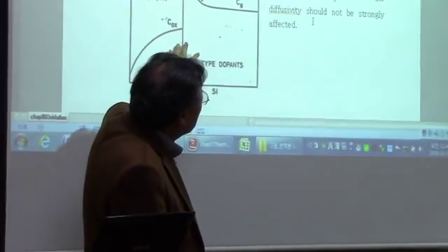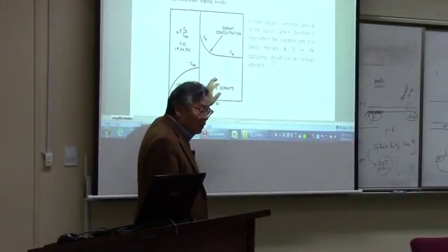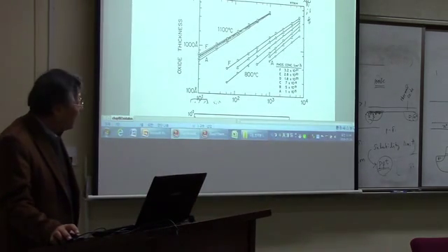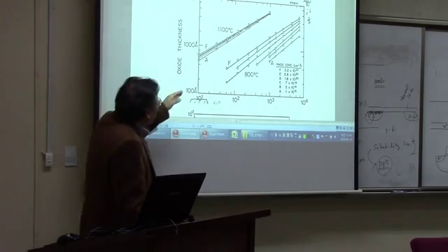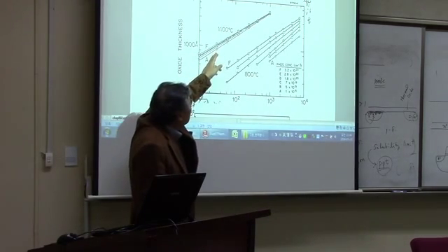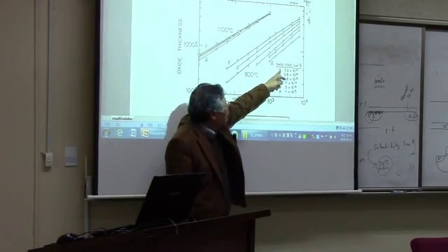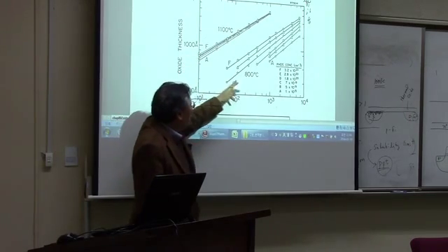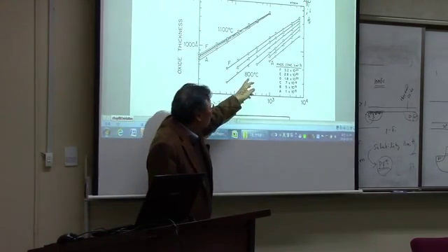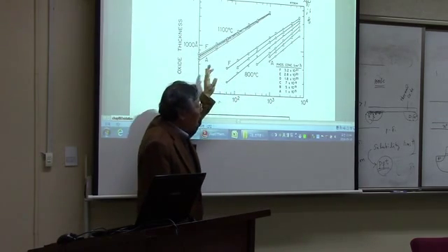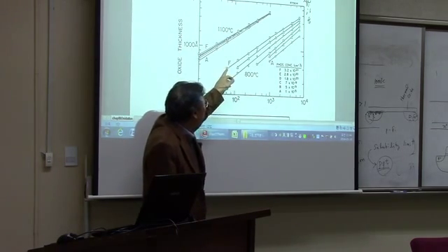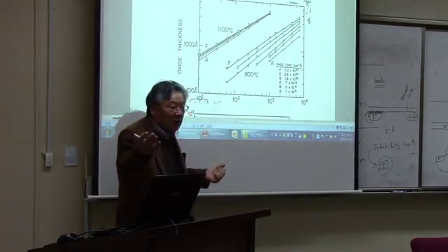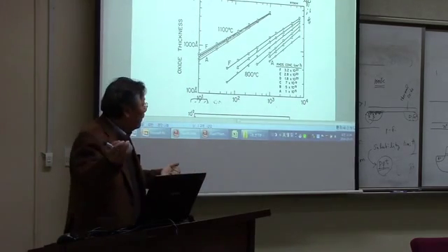And then the section here we're going to discuss is about the dopant effect on the oxidation rate. How does it affect that? This is the experimental result. At an elevated temperature of 1100 degrees centigrade, the phosphorus concentration does not really affect the oxide thickness, as you can see here. But if you lower the temperature to 800 degrees centigrade, now you can see a very different oxidation rate from F to A, okay? This is A, and F is just to increase the amount of phosphorus doping.